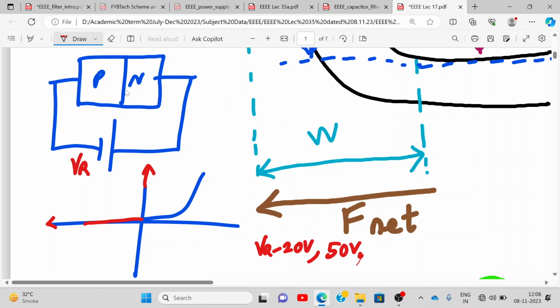Now, that guy has really gone mad and he has increased beyond 100. Now what has happened? The moment it increased beyond 100, your diode has burst, and he couldn't find a reason why. This is an irreversible phenomenon. If a diode enters avalanche breakdown, it will never recover back. It's a waste. So after that 100 volt, your current will increase very fast, and within no time it will burn out. Your current will increase too high, it exceeds the limit rating of the diode, and the diode will be off because temperature has reached very high.